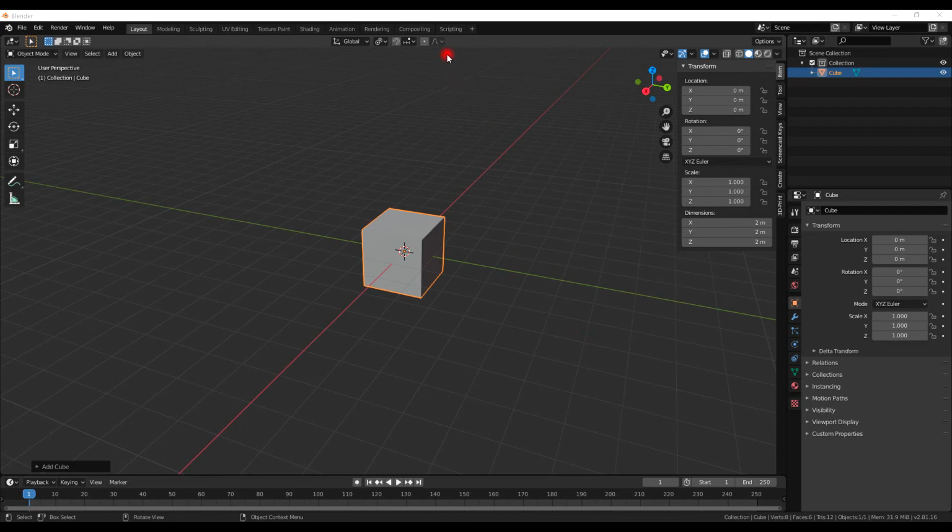And to do that, you have here on the top a snap menu. First of all, there's a snap switch. This is now turned on, and this is now turned off. You can also do most of your snapping by pressing the Ctrl key while you are doing the actual thing that you are doing, like moving the object. So you don't have to have this turned on unless you are doing a lot of snapping. I usually leave it off.